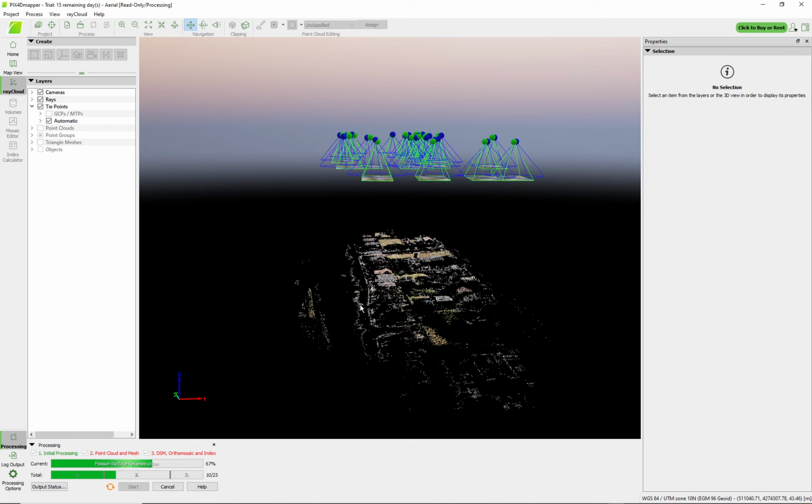You need to be in GPS mode in the sense that the GPS signals are working. You need to be in contact with numerous satellites, and you also need to have the orientation, so the compass of your drone working, and that's as simple as just relocating your drone from being near a metal object to being away from a metal object. So you just do a little bit of a walkabout and wait for the magnetic interference signal that you're getting on your drone controller. You want that to go away. So once that goes away, you can take off and get up in the air. And once you're up in the air, you don't have to really worry about that anymore.